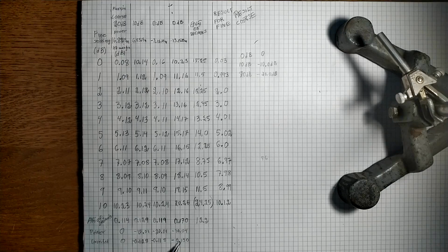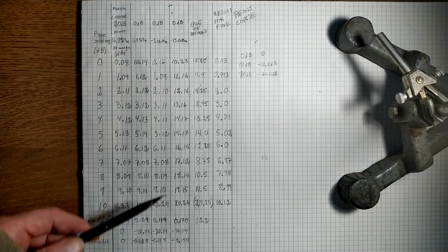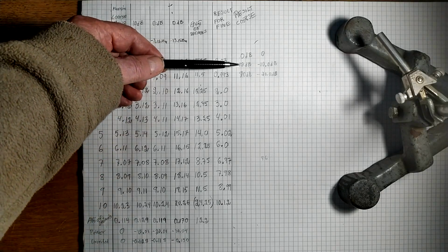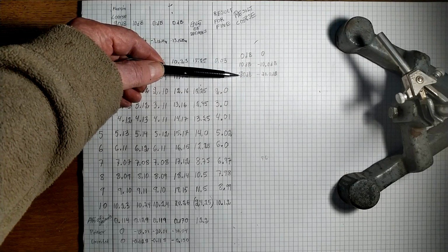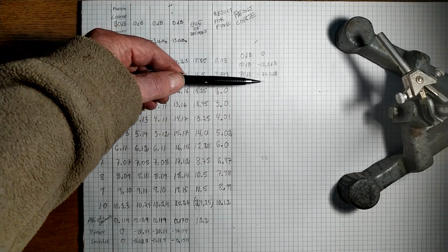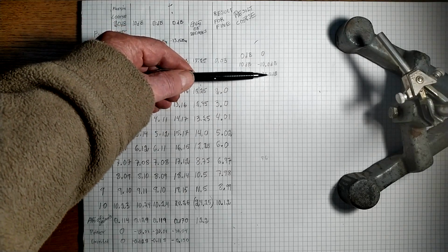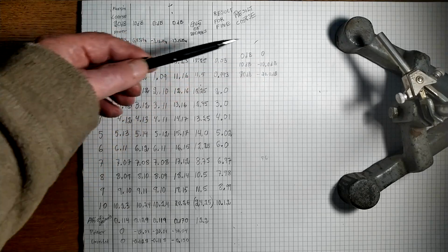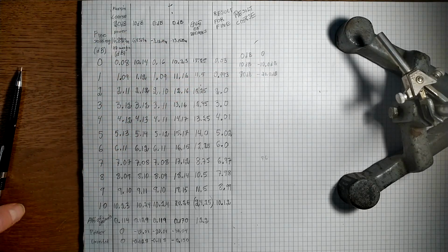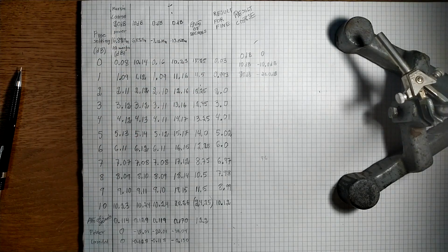Because the level setting on my signal generator is in 0.1 dB steps, and I didn't want to spend more time on this, the result is that the 10 dB and the 20 dB coarse steps are accurate to significantly better than 0.1 dB. So I can just use this attenuator as a precision instrument that facilitates what I'm going to do.